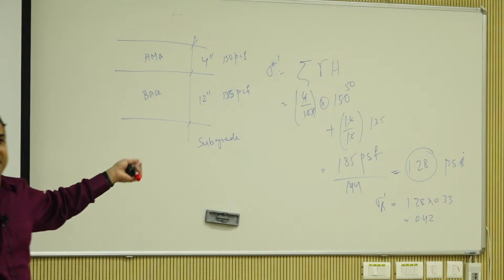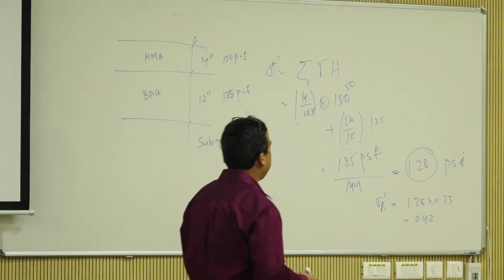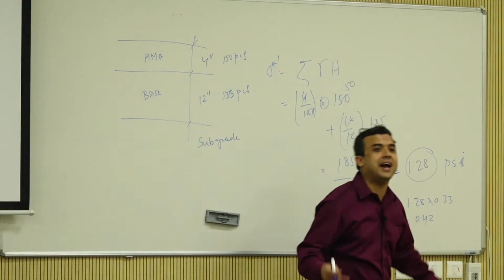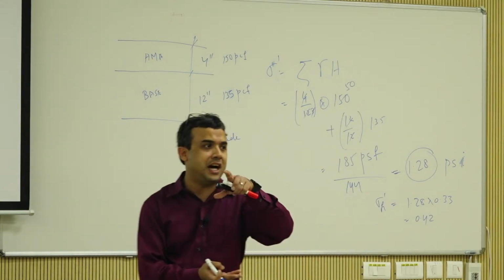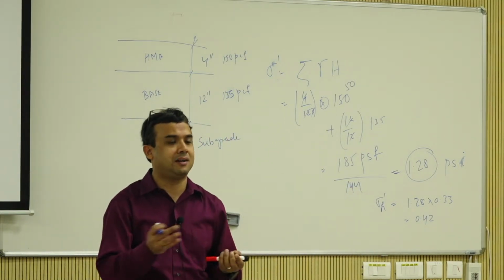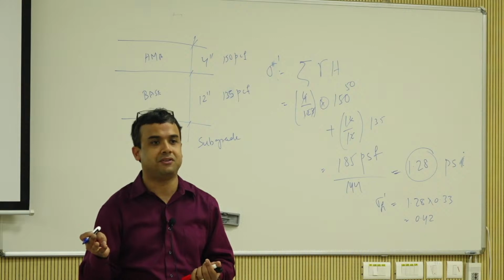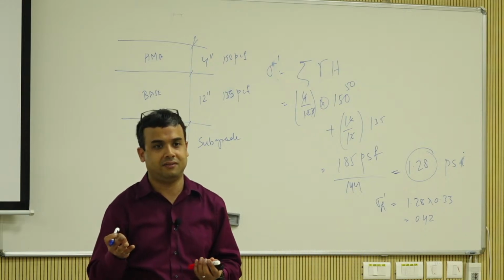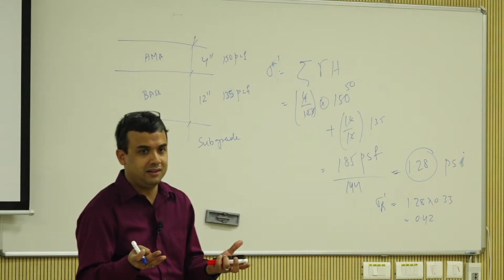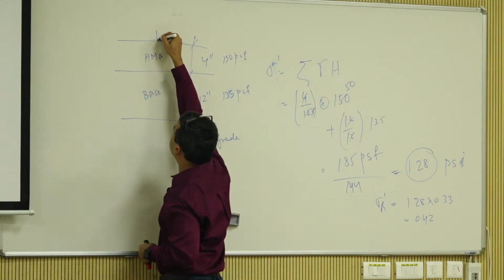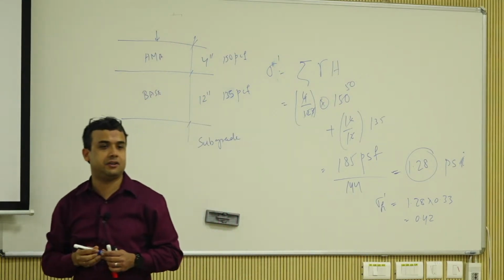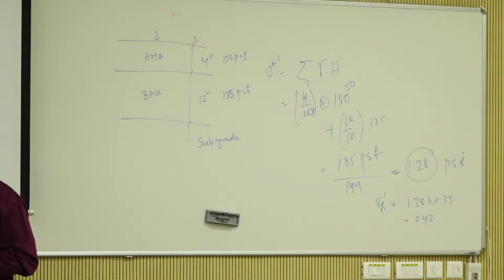Right? So that is the reason your soil is under so little confining pressure underneath the surcharge of a pavement. That's the reason running an unconfined compressive strength test is representative, because it's very low confining, right? So whatever you are feeling is based on the deviator stress. That makes sense?